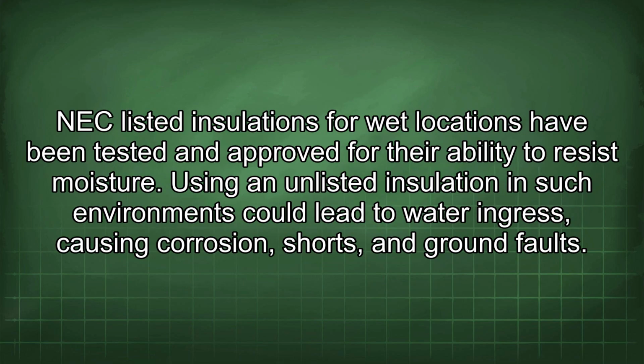In damp or wet environments, the insulation's resistance to moisture penetration is critical. NEC listed insulations for wet locations have been tested and approved for their ability to resist moisture. Using an unlisted insulation in such environments could lead to water ingress, causing corrosion, shorts, and ground faults.